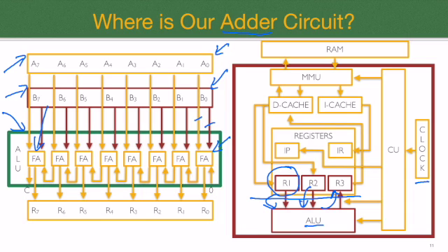Once it is decided that addition is the operation that needs to be performed, the next clock tick will actually connect the output register with the addition circuit, and then there will be another clock tick which will actually perform the addition, bring the value from R1 and R2 and store it back into R3. So this operation will generally get performed in 3 ticks. Actually, there are more than 3 clock ticks that are required to perform this operation completely.